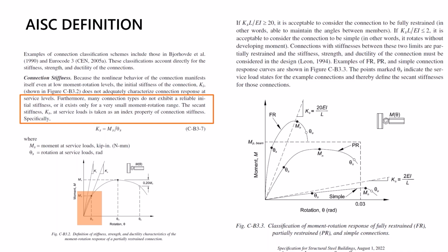For instance, if in the analysis you have the strength load combinations and then the service load combinations, the moment that you will use is the end reaction from the service load combinations. When you use that moment, you are following the AISC requirements, right? That's why it's important to input the correct value in the forces when you're analyzing the stiffness, okay?